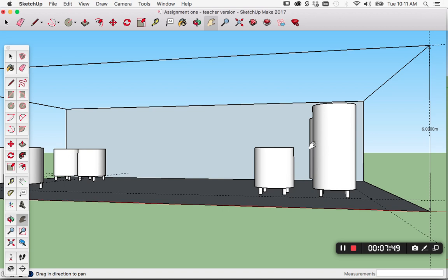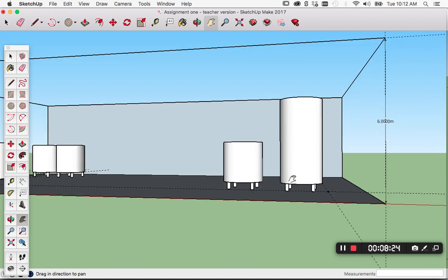On the other hand, when we're doing a flexible line option, the static head is the difference in height of the liquid in our supply tank and the liquid in our discharge tank, because the liquid will be entering from the base. So at the start, our static head will actually be negative, because this tank here will be empty, this one will be full. So this one's actually 2 meters above where that liquid's going. So we actually get 2 meters of pressure for free. So that's a negative static head. So the minimum static head in the flexible line option is actually negative 2 meters.